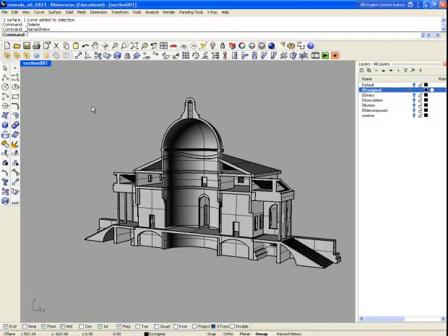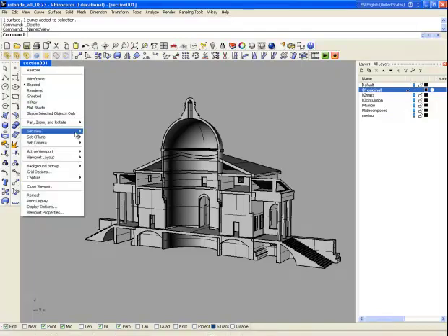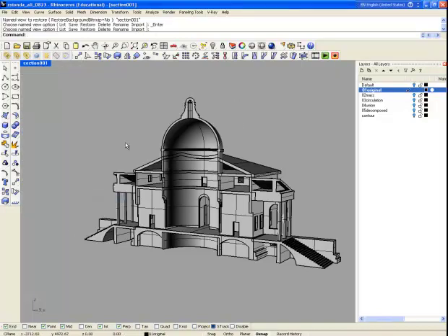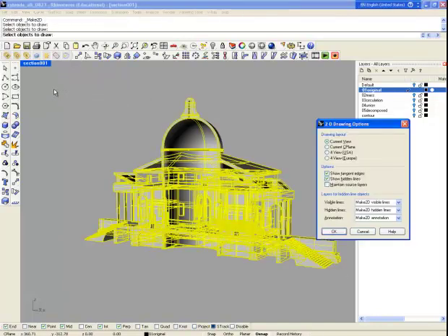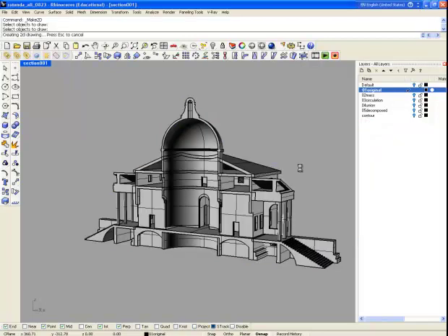And then first thing I want to do before I get into the section hatch, I want to get the outline of the section model as you see on the screen. So in this case, make sure that you have the correct view, right? And then go to Dimension, and to make 2D drawing, select the object to draw. So all of this, enter. And then, okay, current view, hidden lines, tangent lines, and looks good, and okay.